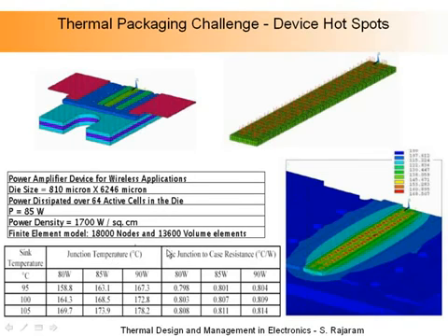Then we measure the temperature of the case. That is where it is mounted onto a heat sink. And we define a thermal resistance shown by these numbers. And as you can see, for 80 to 85 watts, depending upon the sink temperature, that is the mounting surface temperature, the junction of the device can reach anywhere from 158 degrees that is shown here all the way up to 175 degrees. So this is above the limit at which these devices can function. So this is just to give you an idea that the numbers that we are talking about are real. So the power levels and the densities are extremely high.